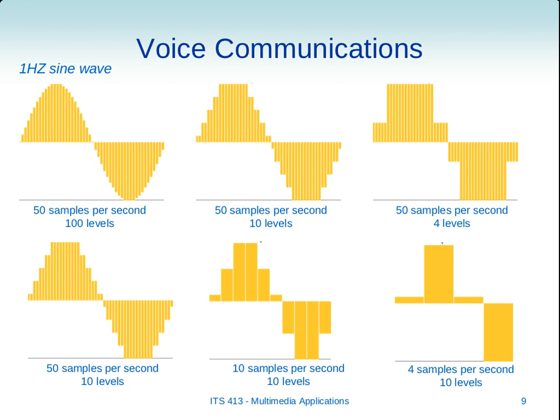6 different, very simple sampled signals reproduced at the receiver. So imagine what's happened. At the sender, there's been some analog input, which was a sine wave. It was sampled at some rate and with some sample size. The bits were sent across the link or across the network. The receiver received those bits, takes the sampled bits received and generates some analog output. And these 6 diagrams show the analog output which is produced.